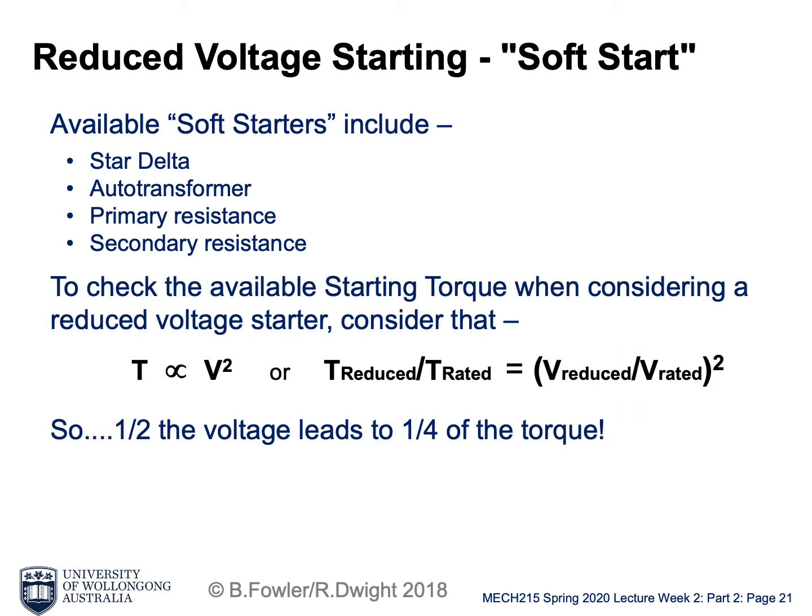Things to remember: when we do soft start, because we reduce the supplied voltage, the torque from the motor is also reduced. Remember, we have a pull-up torque, which is the lowest point during the startup. When we do this soft start, we have to make sure that the lowest torque, the pull-up torque, is bigger than the payload torque. That guarantees that the motor can actually start. Otherwise, if the torque is less than the payload torque, the motor will never be able to start. So again, there must be a better way of addressing this.